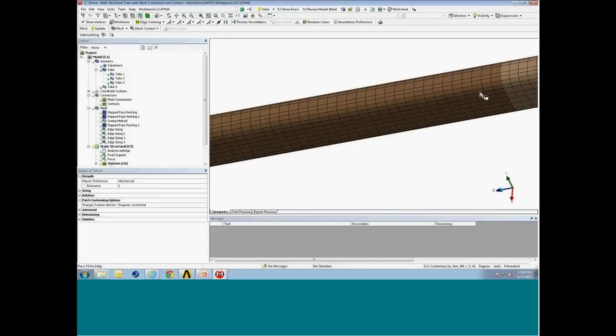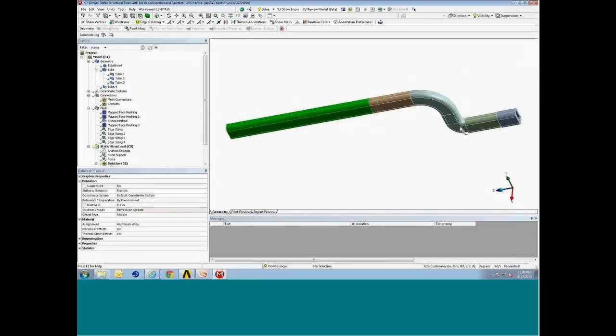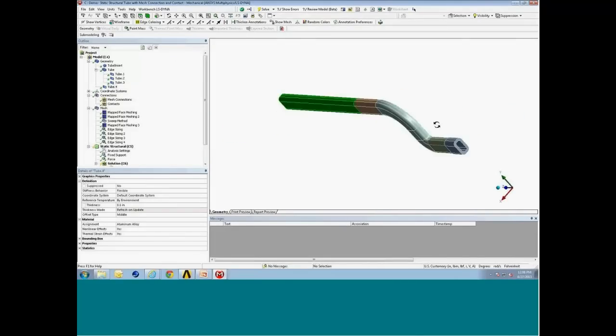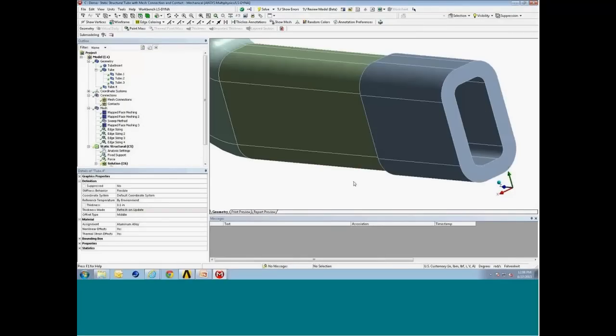I also want to show that with each surface body, an important part is the offset. The offset controls this: typically, surface bodies are modeled at the mid-plane of the solid that you may be extracting. Surface bodies are great for creating shells to model fairly thin to moderately thick structures. But by default, the actual element geometry is in the middle of the shell thickness.